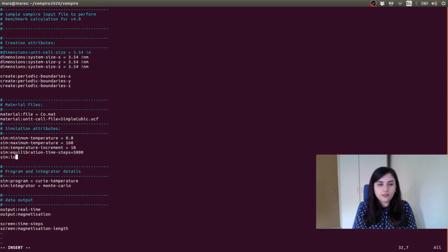And then we need some time step over which we are going to do the average of the property. So this is for statistics. Loop time steps, again 5,000. This is quite a small number, so for each individual system we're going to simulate, you need to do some very fast tests in which to see if your system is equilibrated long enough or not for these numbers here.